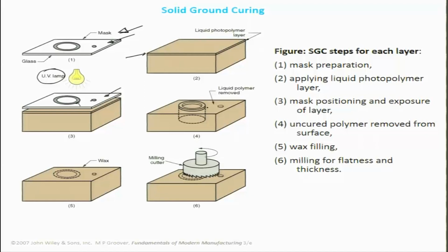Okay, and in this particular case, if we use a positive resist, you can think of the positive photopolymer to be debonded as light falls over it. So wherever the light is falling down, the photopolymer would be dissolvable, so it can be dissolved away, and wherever the light is not falling, there is going to be a resultant structure or a feature, a 3D feature in place.